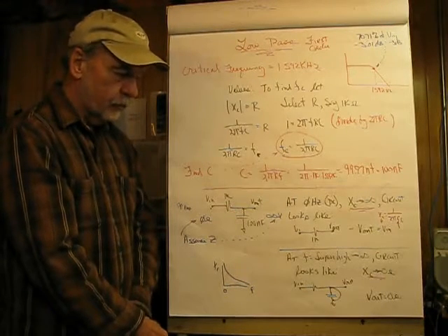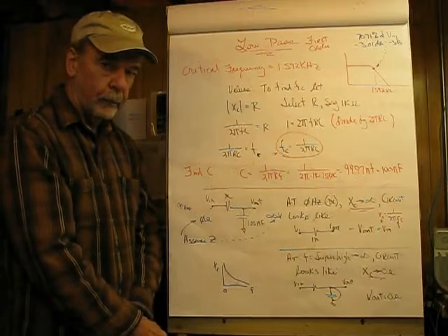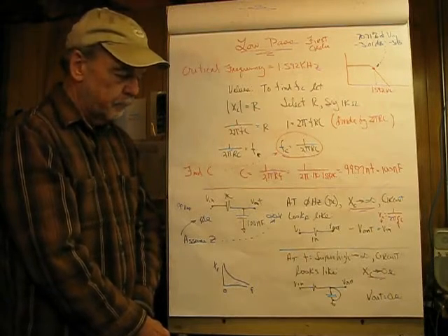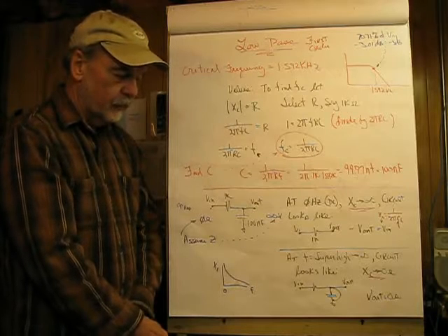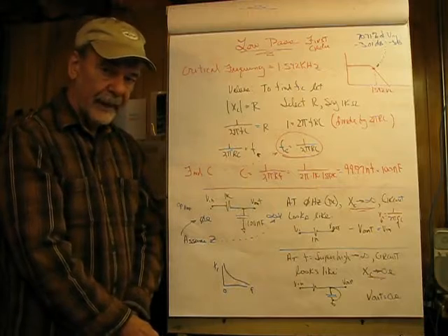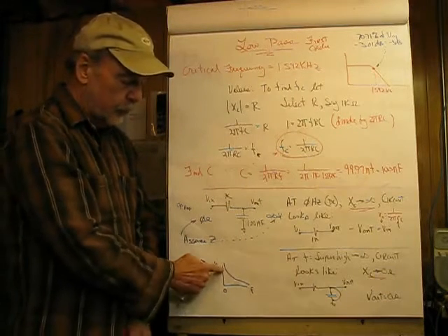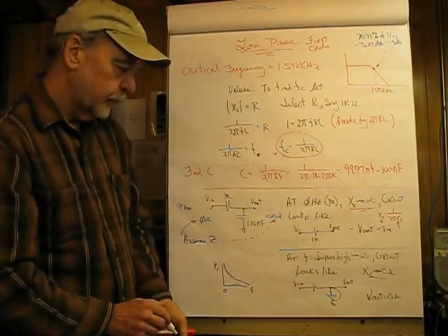So capacitors are good for blocking DC, as you see on your scopes when you have direct couple, meaning that DC will be displayed on the scope, or AC couple, which means that there's a capacitor in series with the scope to block the DC, and it's based on this principle here.